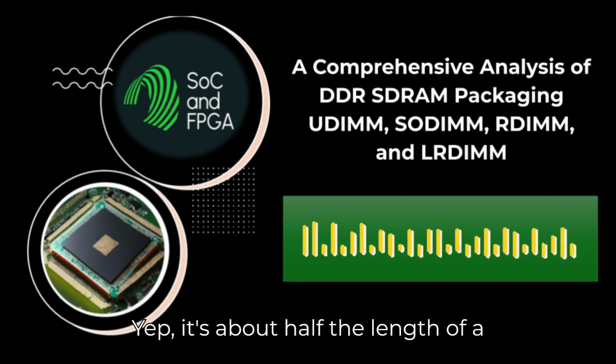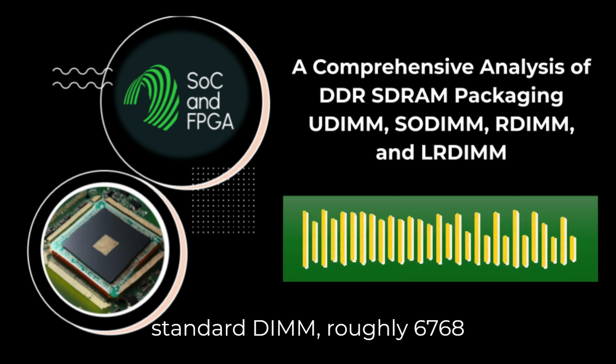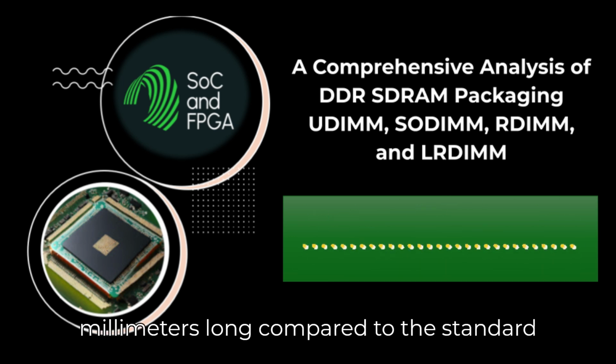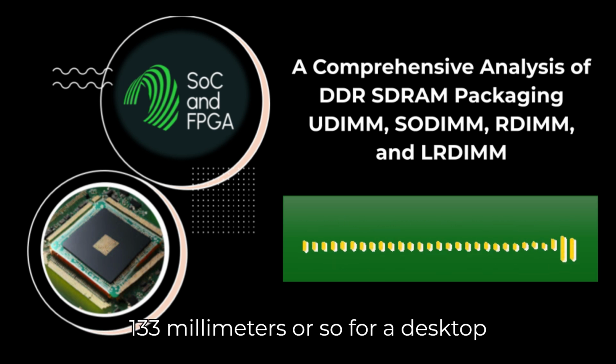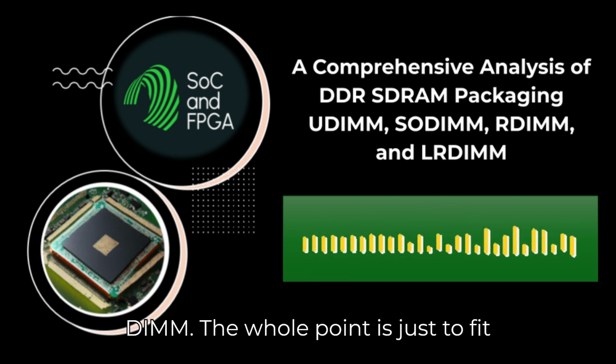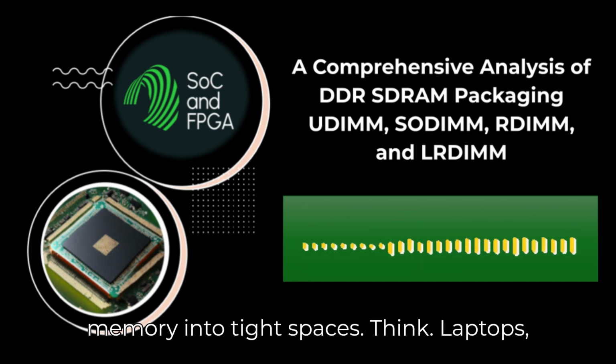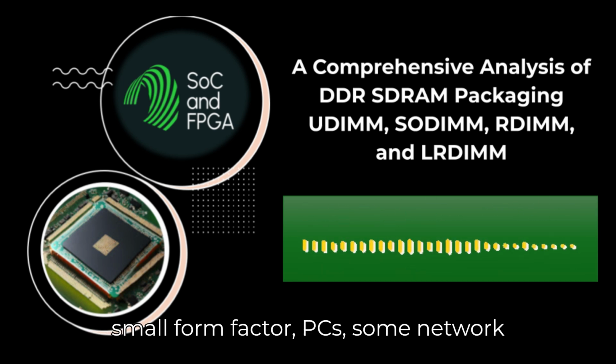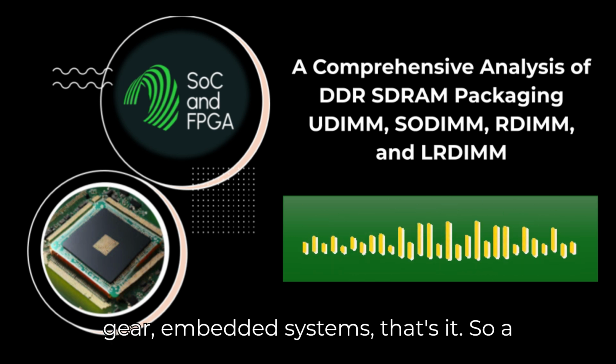Yep. It's about half the length of a standard DIMM. Roughly 67, 68 millimeters long, compared to the standard 133 millimeters or so for a desktop DIMM. The whole point is just to fit memory into tight spaces. Think laptops, small form factor PCs, some network gear, embedded systems, that's it.